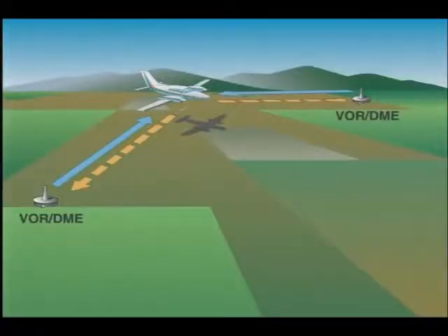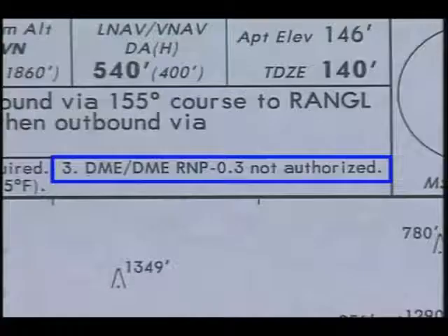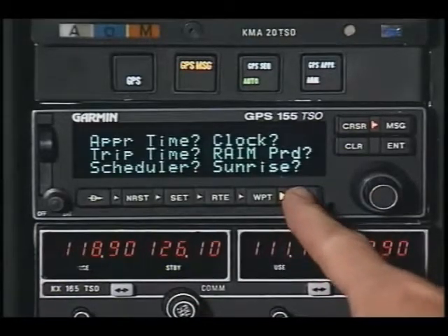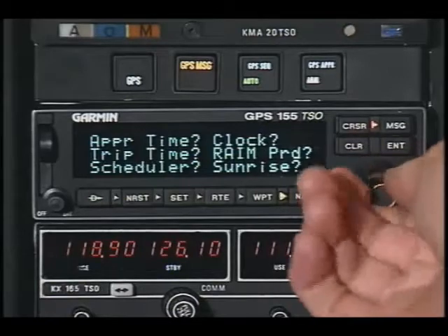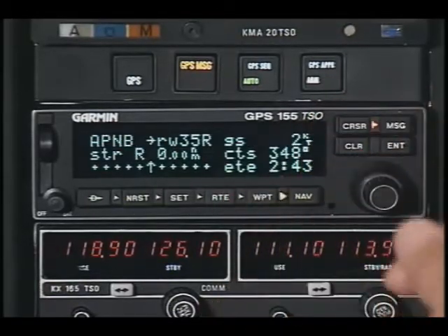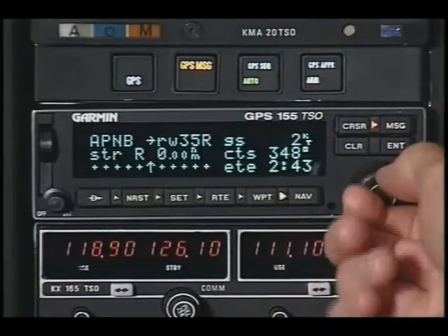Some systems calculate lateral positions based on DME readings. If your system operates by DME triangulation, you are unable to use the LNAV VNAV minimums for the Yankee runway 15 right approach. Since every system operates in a different manner, you must have a thorough understanding of the operational capabilities of your GPS or FMS system in order to comply with these requirements.